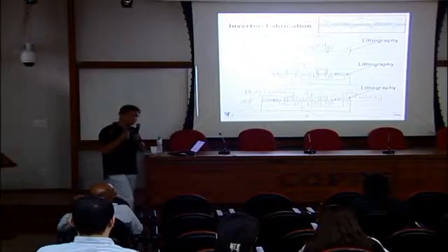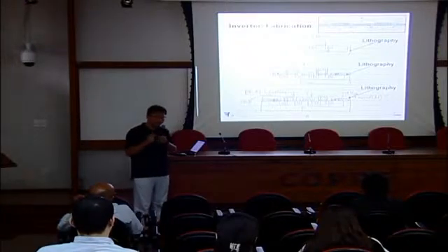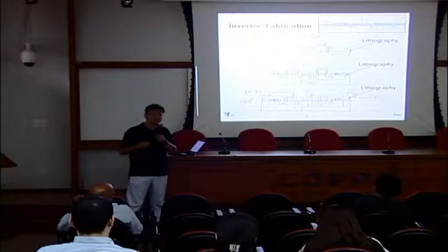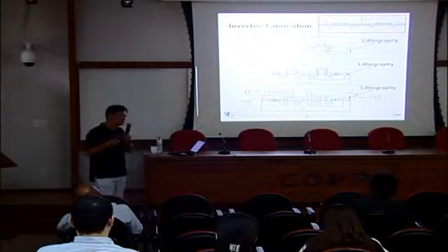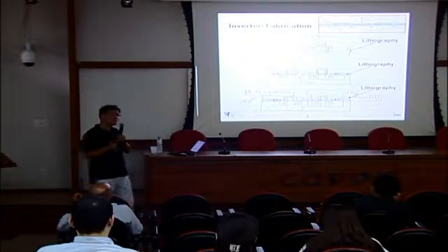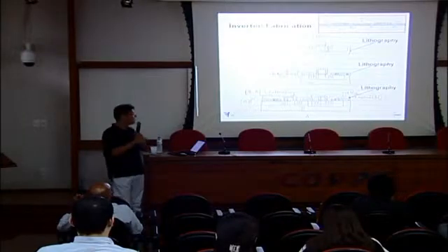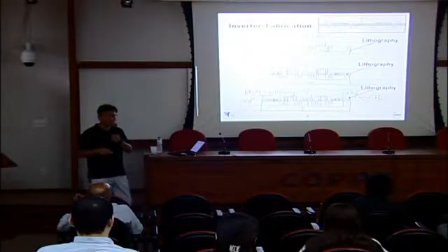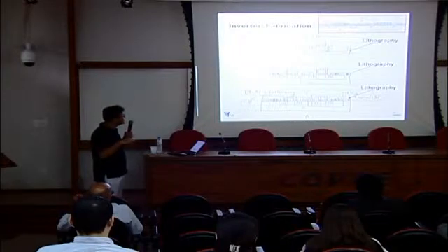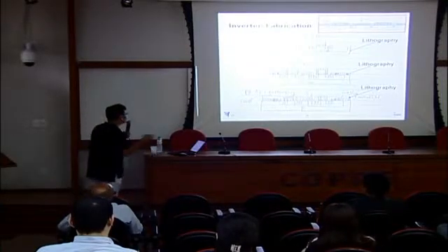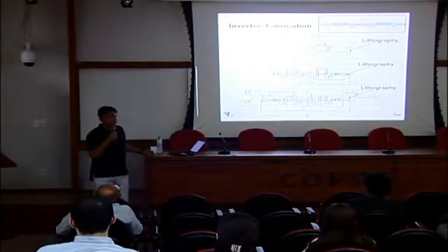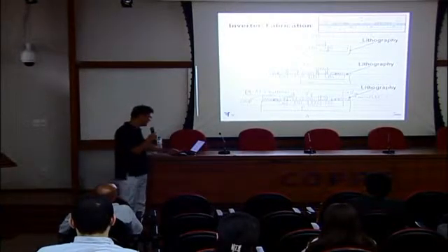Okay, if the yield of one lithography step is 90%, then after 6 steps of lithography, we will have about 50% yield. But you know, for example, my students working on this process have about 5% left after 6 lithography steps. Okay, because it's quite hard. We have to align the mask very precisely onto this silicon wafer. So at each step the yield is only about 70 or 80%. Then finally, nothing is left. Right?